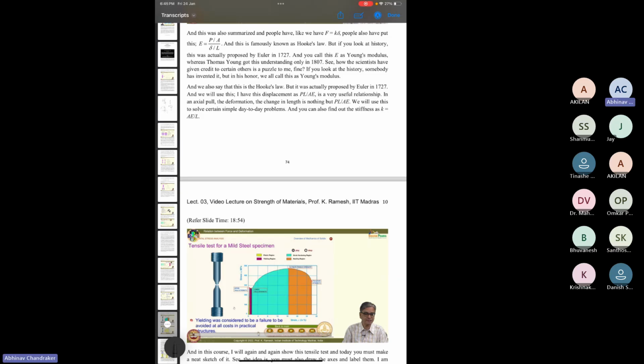The stresses for all three cross sections will be uniform. Yes, the stress strain diagram for all three varying cross sections will be uniform. Okay. But what I'm saying is, the cross section with more neck region will fail first, and accordingly, the next failure will happen. So the fracture limit will change for different cross sections. Then how will the stress strain diagram be uniform for those three different cross sections? I have this doubt.